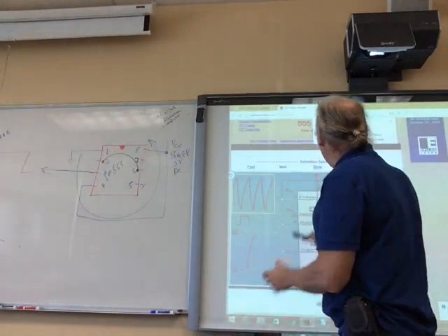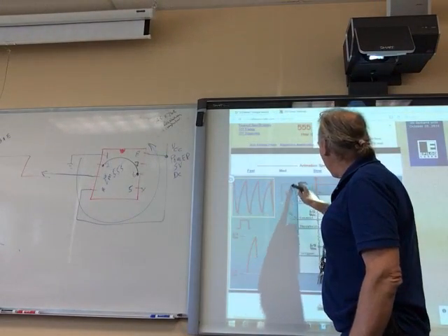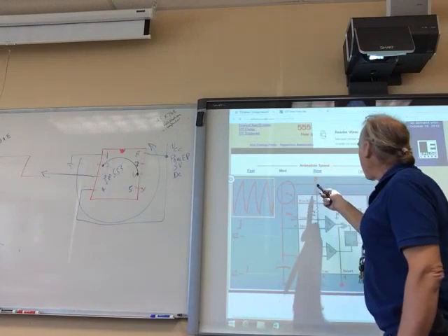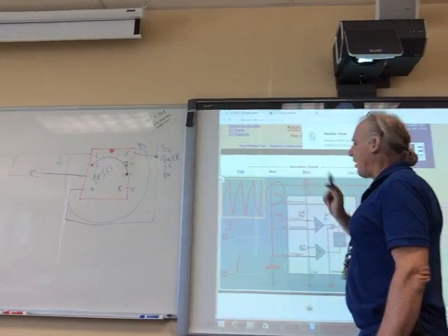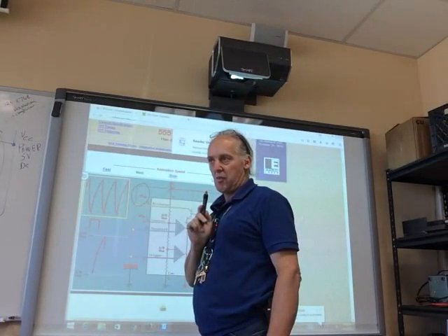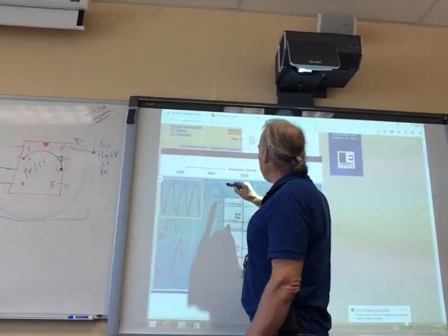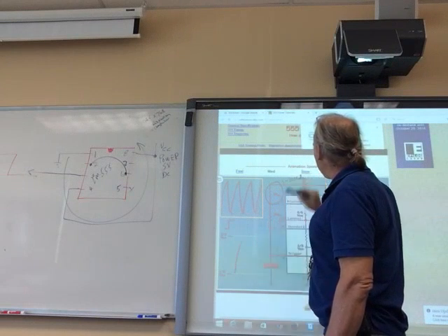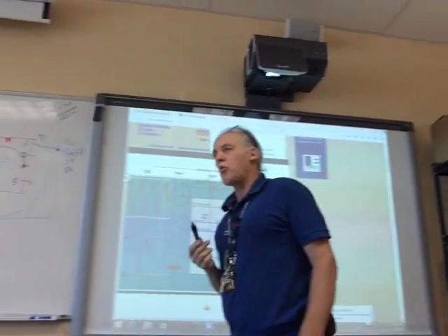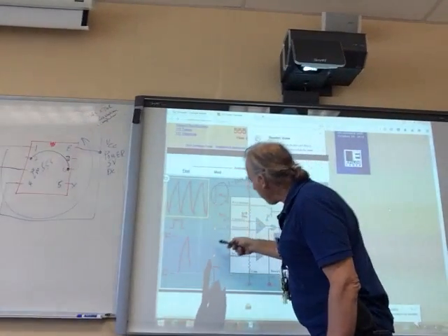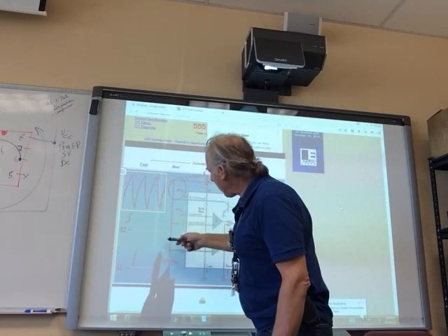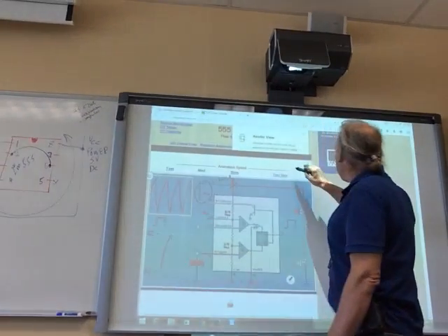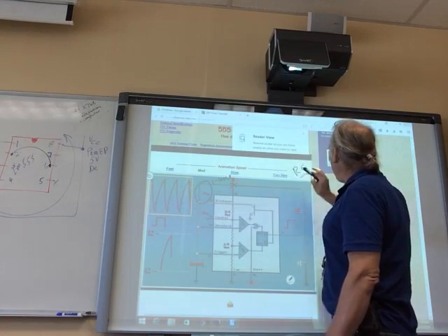This resistor right here is connected to B plus here, 5 volts. Okay? Usually you can get away with a 1 to 10 k ohm resistor there. What does it do? It charges this RC network here. This is an RC network.